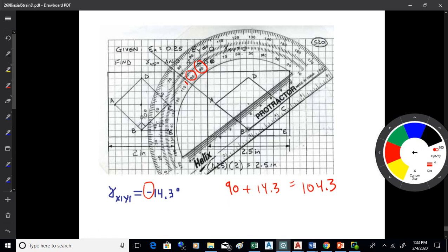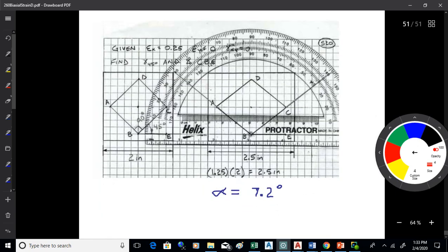And then similarly, that line BC is supposed to rotate 7.2 degrees. So there you go. Over here on the left, BC is at 45 degrees. It's going to rotate clockwise, so that'll make it less. So what is that, 37.8 degrees? That's what I would expect it to be now. Here's 30, here's 40, it's 35. So it's about 38. It's not exact, but all the same, not bad, okay?